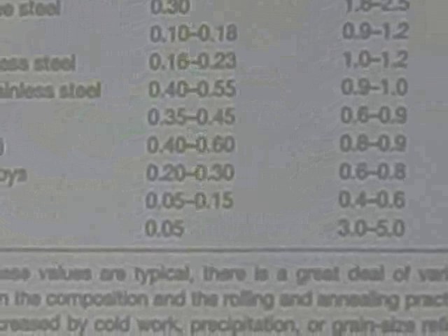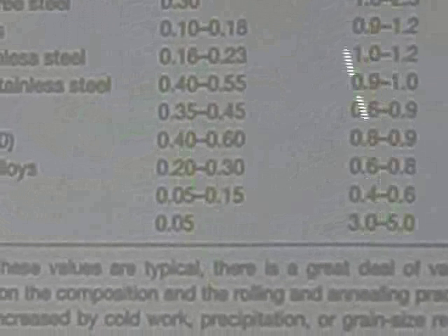We've been talking about sheet metal properties, and we're starting to talk about superplasticity. We have N values, R values, and M values. N is the work hardening coefficient, R is the anisotropy ratio, and M is the strain rate sensitivity of the material. And superplasticity, we looked at the forming limit diagrams.